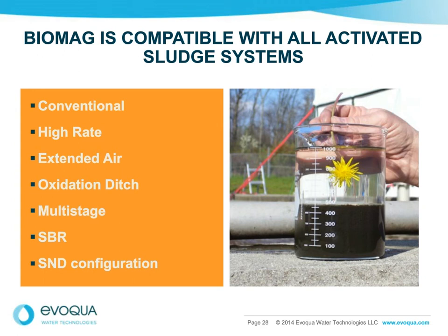Now, one of the advantages, because we are able to run at a much higher sludge age and get an enhanced process here, is quite often we can drive what's called simultaneous nitrification-denitrification. And I won't spend time today getting into that, but it allows you to get more enhancement out of your process, more nitrogen removal, and more stable effluent quality.